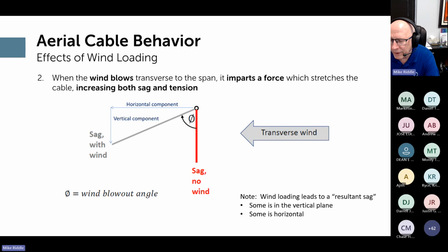What you are likely to fail a cable from is aeolian vibration. That's because it subjects the cable to changes like a factor of 1,000 greater than just normal everyday changes. So you do have to be concerned about the fatigue limit of the materials. In the real world, what it generally works out to is that the aluminum is the one that causes you trouble.